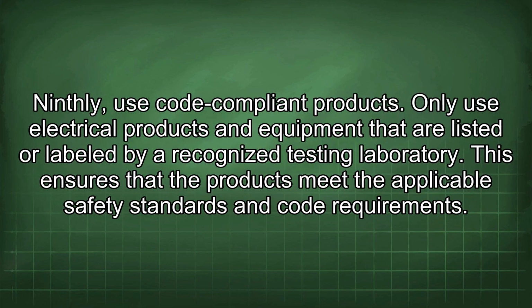Ninthly, use code-compliant products. Only use electrical products and equipment that are listed or labeled by a recognized testing laboratory. This ensures that the products meet the applicable safety standards and code requirements.